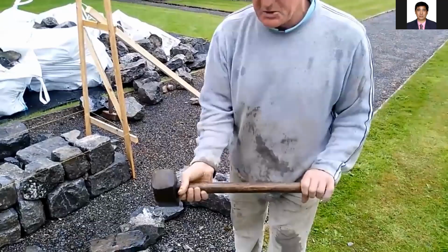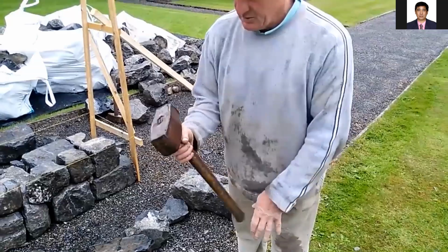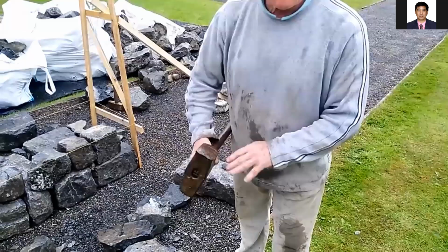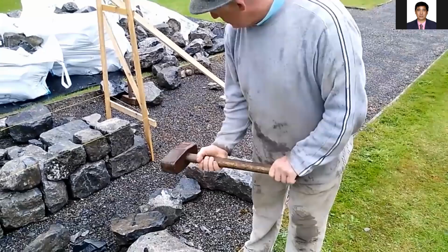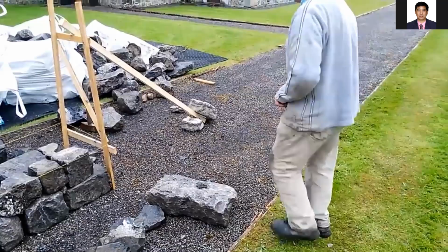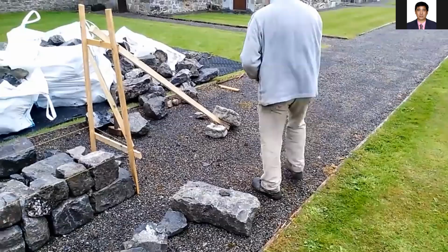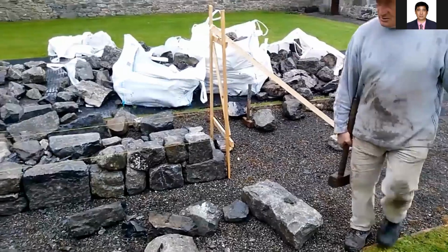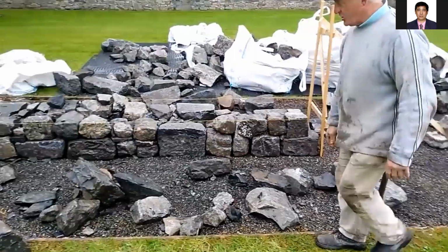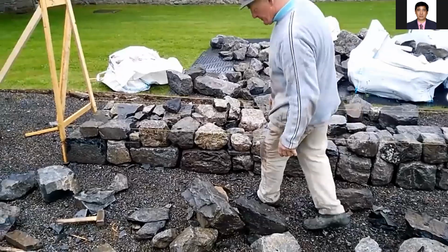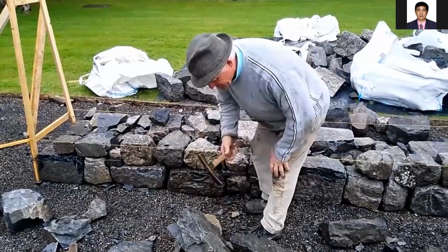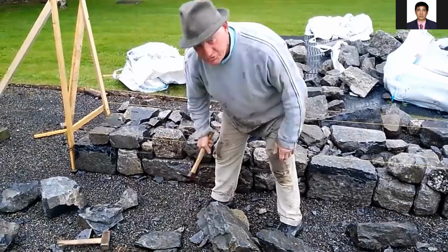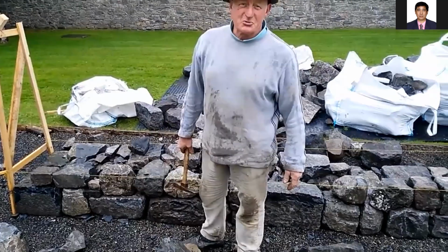Big, heavy hammer for splitting stone or for breaking stone. And this end here is tempered, hardened, and this is left soft. And that's for shaping big stones, or you'd be able to put stones in half, let the backs off the stone. And then you have your smaller hammers for shaping a little bit and taking three faces on and basically just chipping and squaring stones up. That's the only tools you need, and a piece of string.